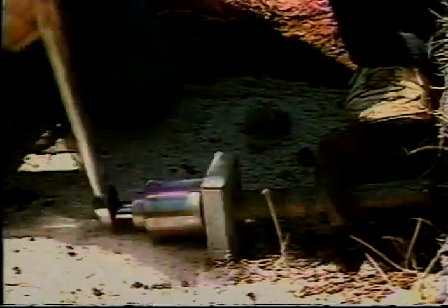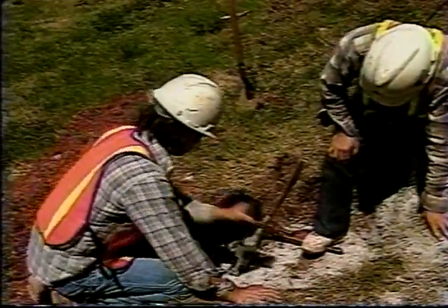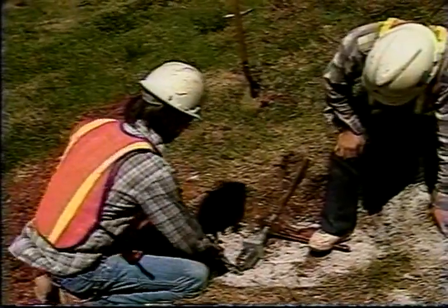Tighten the cable by holding the swagged end with a pipe wrench and torque the nut with a torque wrench to 100 foot-pounds. The nut threads need to be fully engaged to the threaded cable ends.